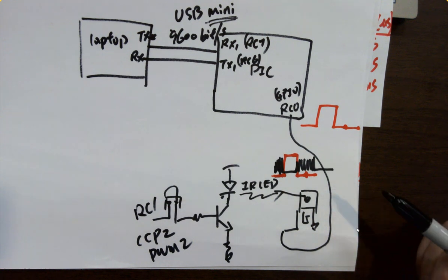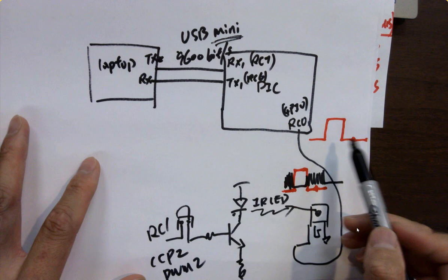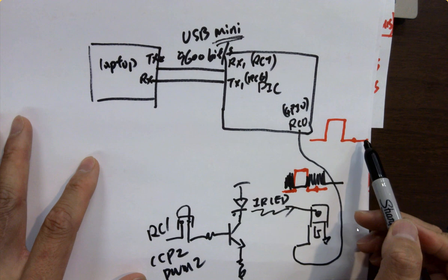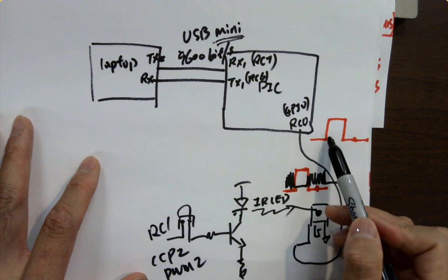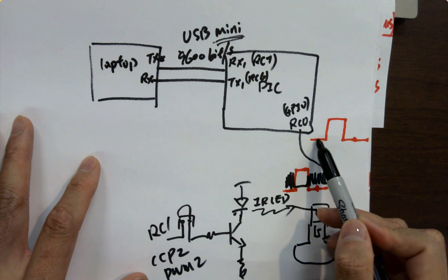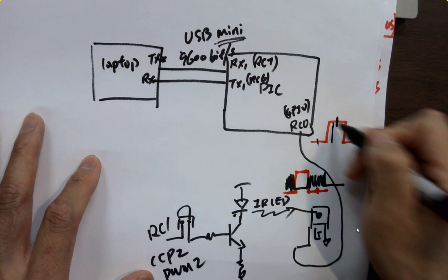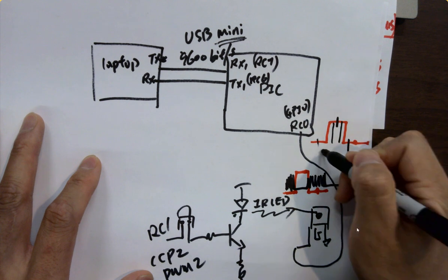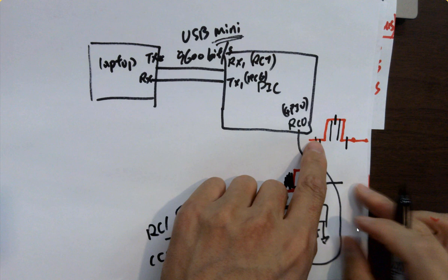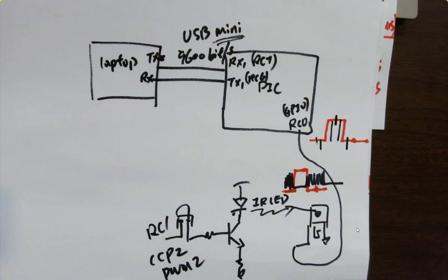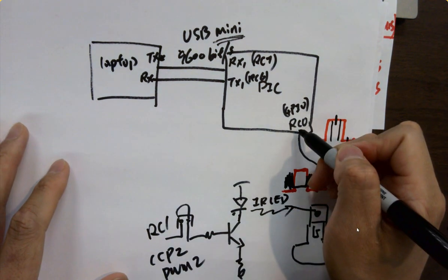You can do it in millions of different ways. You have to know the certain protocol time delays, that this is 1 bit and this is 2 bits. So right here we got 4 bits instead of 1, 2, 3 bits. So RC0 cannot do the job.